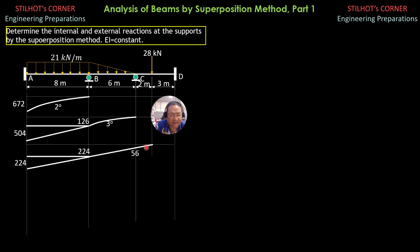At C rather, we have a couple of 28 times 2, concentrated load of 28. So that's why 56, and the moment due to the 28 kilonewton load at B would be 28 times 6, so that's 224 minus 56. So EI delta B due to the loads, we will only consider this part. This moment diagram by parts will have contribution to the deflection at B.